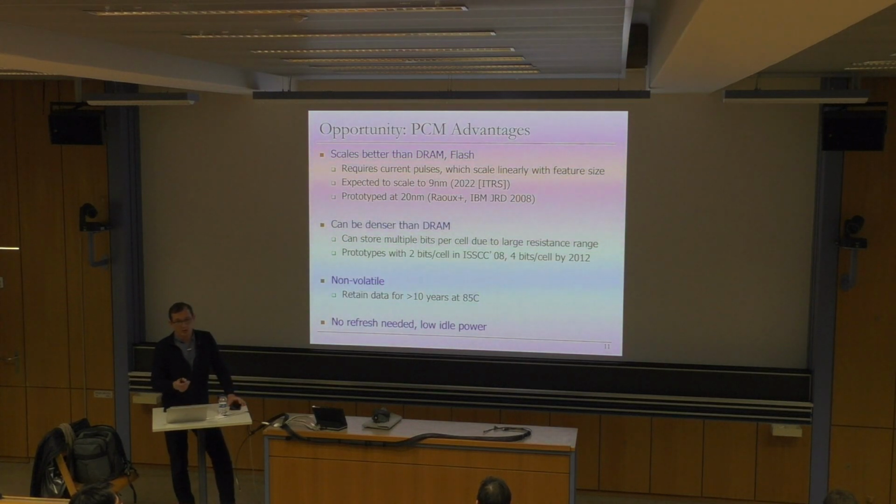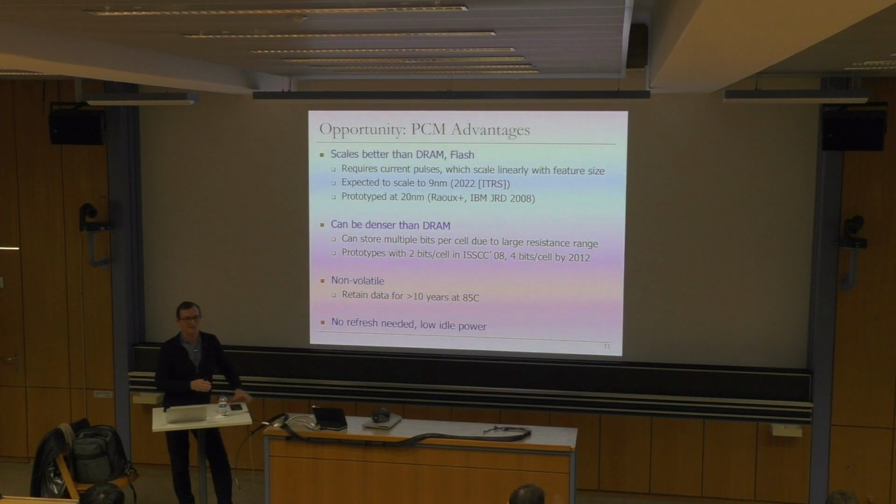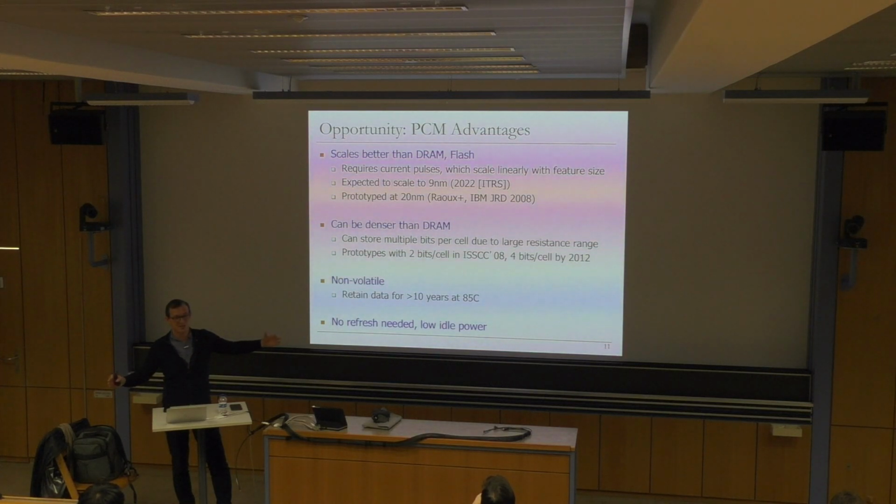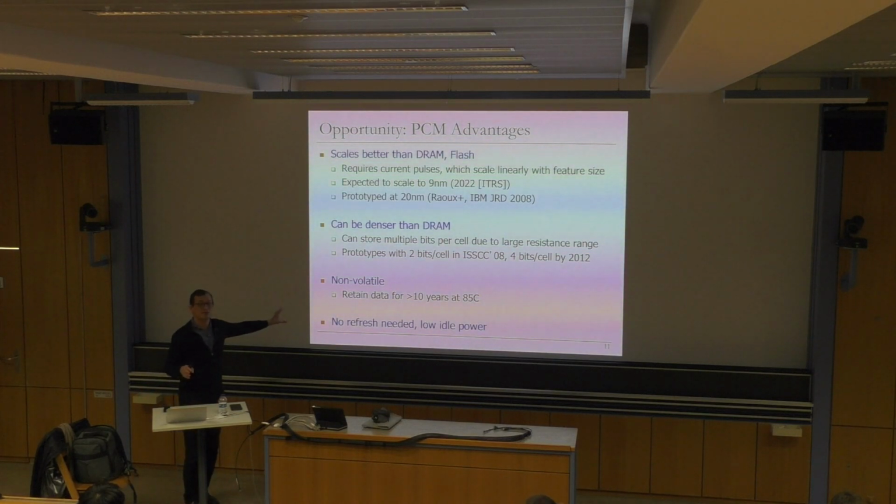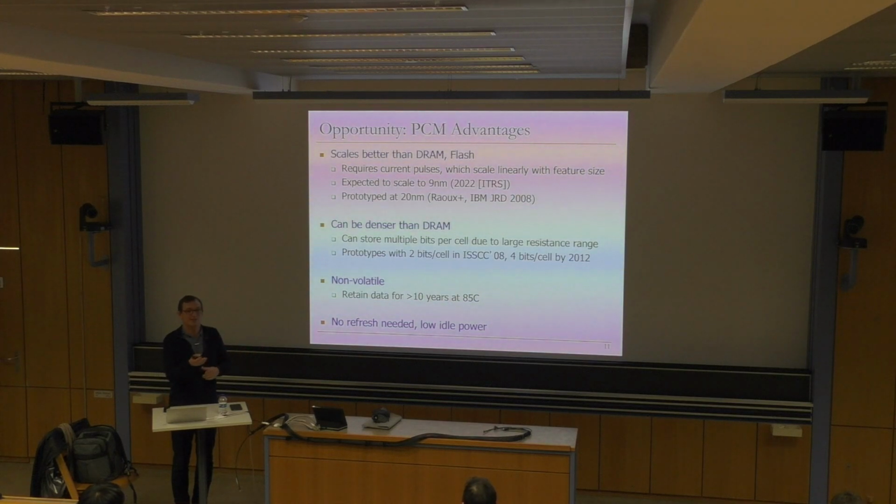Yeah. So in terms of cost per bit, over time it's expected to become cheaper. Yes. If you do the scaling calculations, if you invest the same amount of money into manufacturing, this is definitely going to be cheaper. No question about that. But DRAM is currently at a point where a lot of investment has been done in the manufacturing technology. And the manufacturing technology is so precise and so optimized that its cost per bit is relatively low right now. Does that make sense? But over time, this is expected to be much better because of scaling, essentially you can cram more bits in a given area.